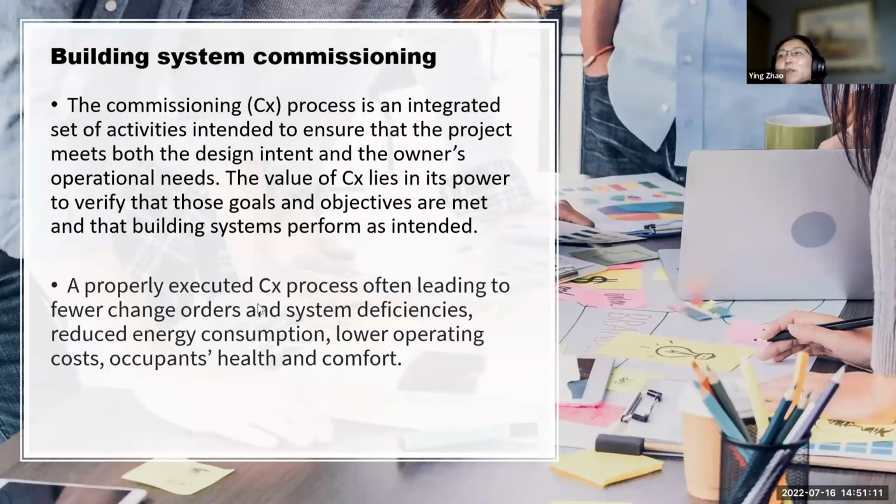A properly executed commissioning process often leads to fewer change orders, fewer system deficiencies, reduced energy consumption, lower operating costs, and higher occupant health and comfort levels. So that's essentially just making your good design actually perform.